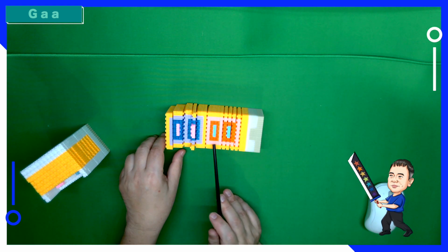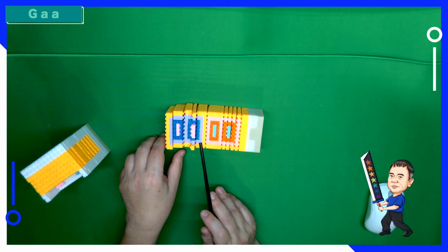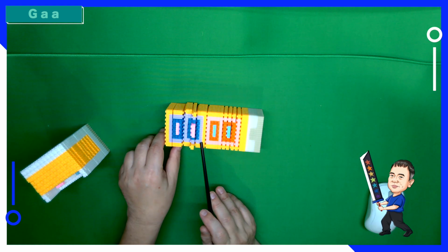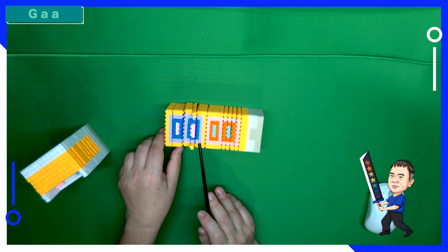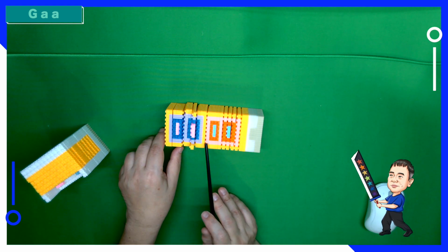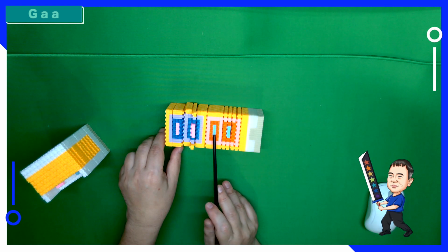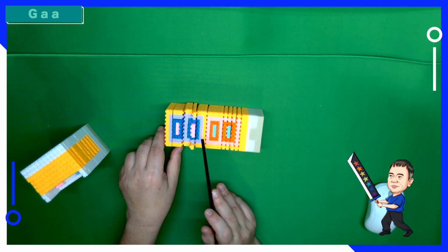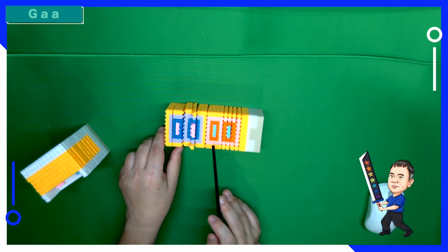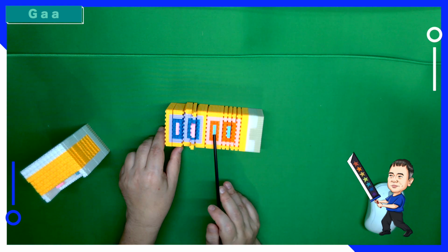This pink color and the purple color actually stand for different metals with different work functions. They are all metal, but they have different work functions. So when you apply high voltage to allow the N channel to flow through, or low voltage to allow the P channel to flow through, you have better control from the gate to the channel.